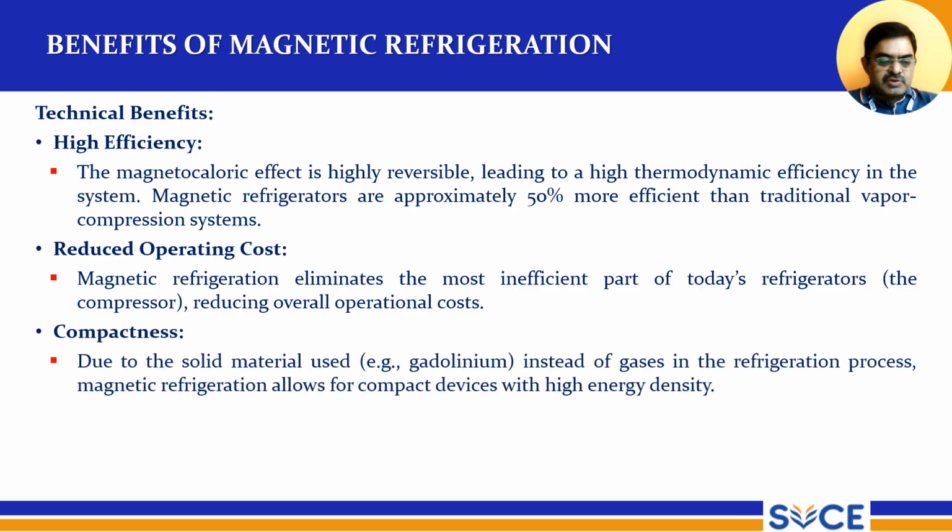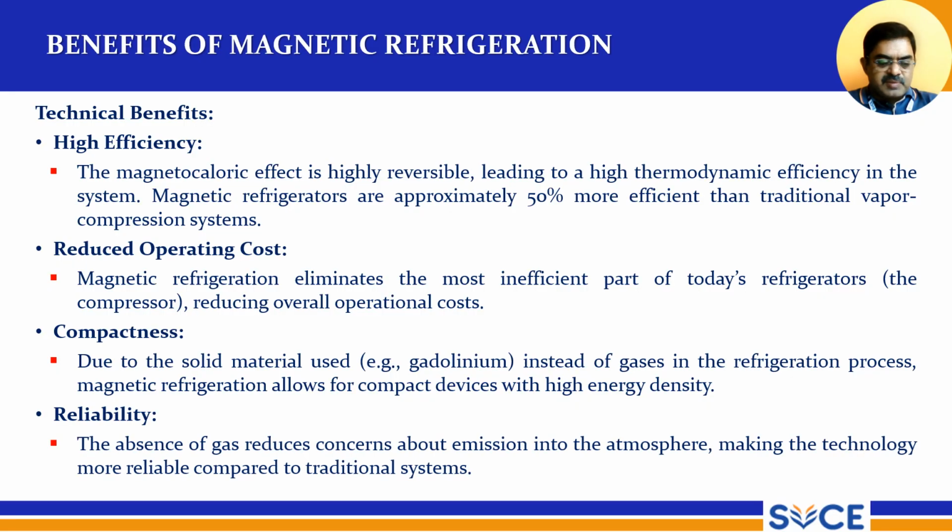So compactness. Due to the solid material used, gadolinium instead of gases in the refrigeration process, magnetic refrigeration allows for compact devices with high energy density. The absence of gas reduces concerns about emission into the atmosphere, making the technology more reliable compared to traditional systems. So that is the reliability of this system.